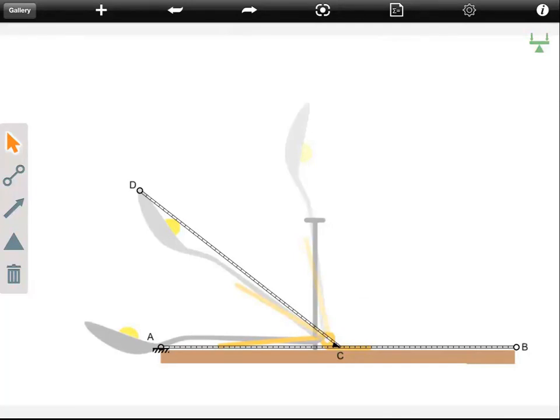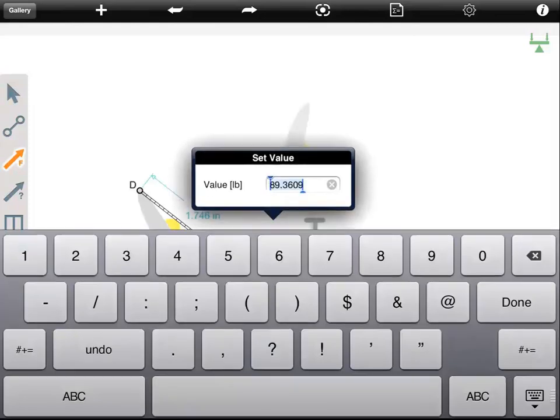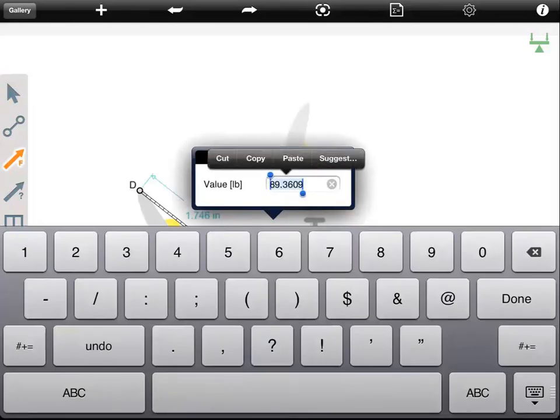Now that the throwing arm is welded to the base, we can add the force required to pull the arm back on our Mousetrap. We can do this by clicking on the Loads menu, and then tapping and dragging a force near the endpoint of the throwing arm. You'll notice as we drag along the screen, the force does snap to a perpendicular location, and when you release your finger from the screen, you can enter your exact value. In our case, the force was 1.13 pounds of force. If you measured your own force, you'll want to enter that here at this point.